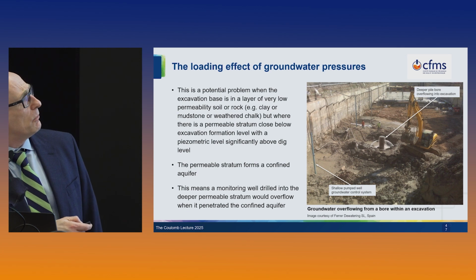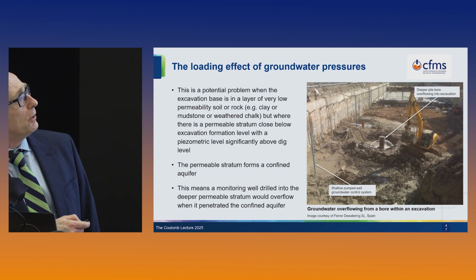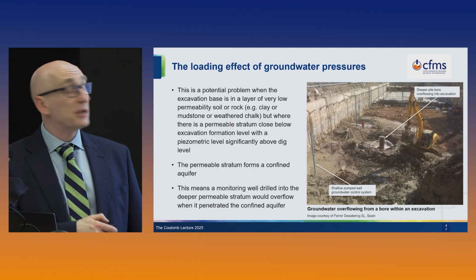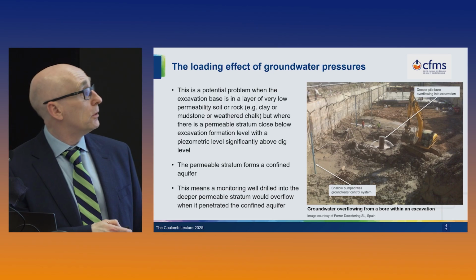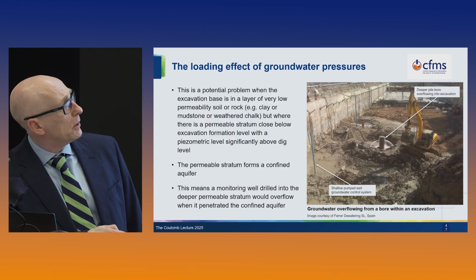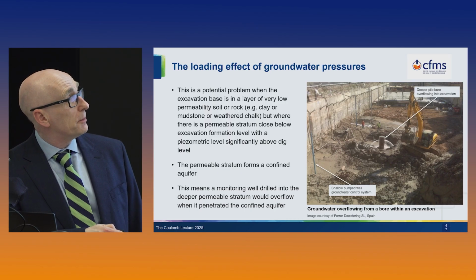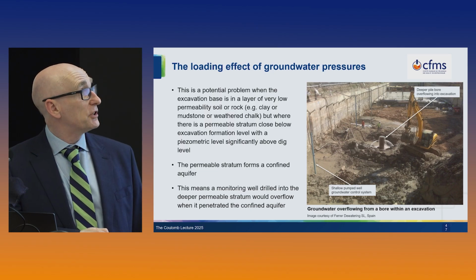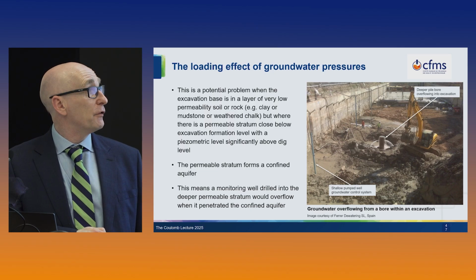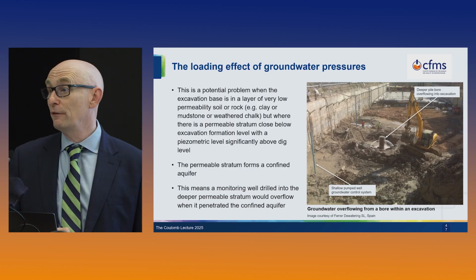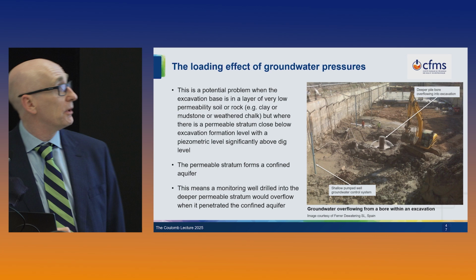So we've got an excavation that comes down to here, and it's supported within concrete diaphragm walls. The blue vertical pipes are pumping wells because there must be a shallow aquifer here that's been dewatered. You can see it's been dewatered. This excavator's in the dry. There are operatives working here. But what they've done is they've drilled a pile bore in steel casing downwards, and they must have penetrated a confined aquifer below them. And you can see that this pile bore is overflowing quite aggressively, quite strongly.